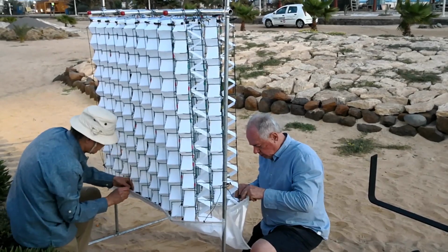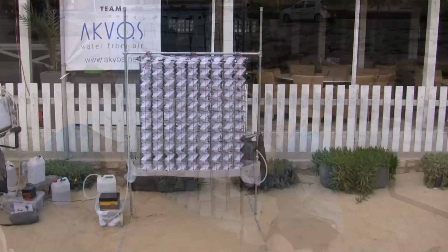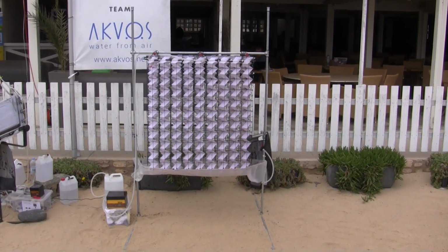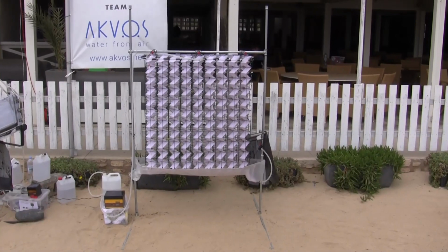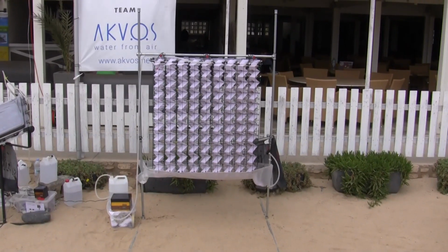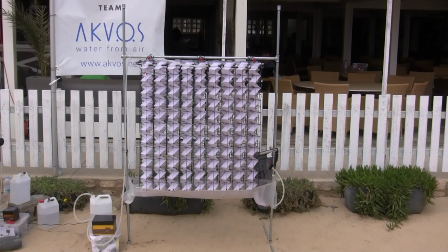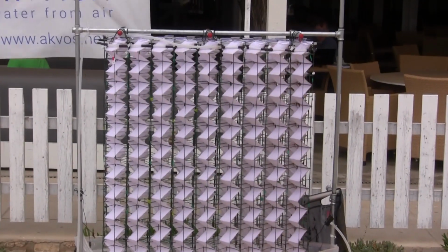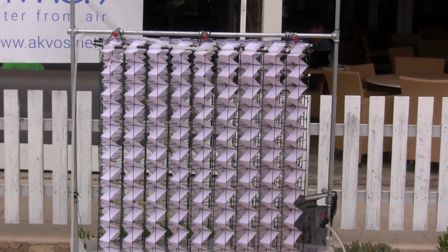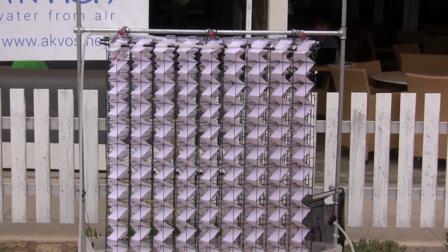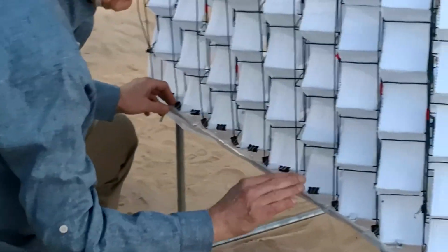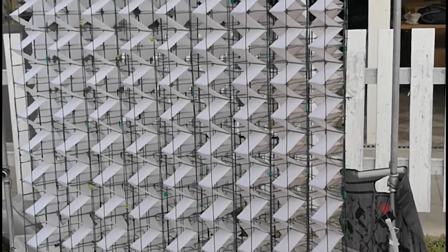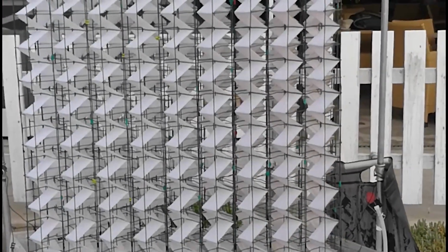This is the water absorption module. For this trial we use an open wireframe structure holding 9 square meters of absorption surface made of cotton stripes. This structure is based on 4 segments. Each segment has a size of 110 centimeters times 100 centimeters times 11 centimeters and holds 9 bands of waffle cotton textile. Each waffle cotton textile band is 212 centimeters long and 6 centimeters wide.